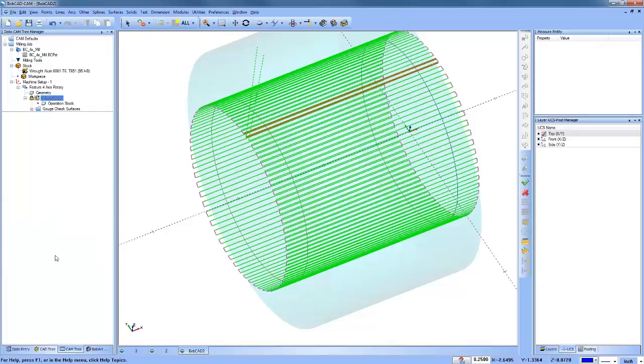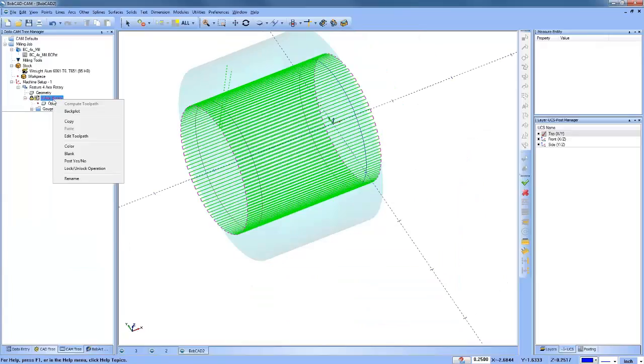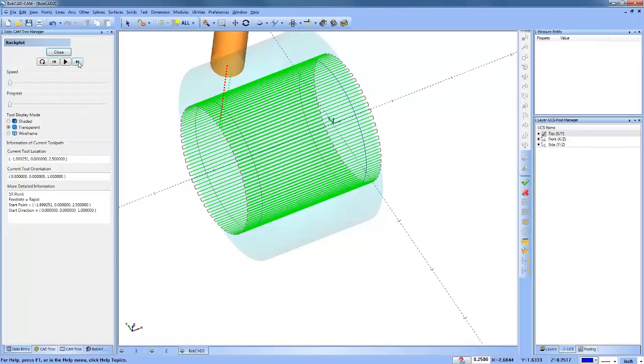Apply all. Okay, so what we've done is on this cut here, this first move, we've slowed down the feed rate. Then after it gets through this section here, it's going to speed up again. So as it's engaging through that first cut, it's slower, and then once it gets into the cut, it can speed up its speed rate. That's just a quick example of how you can edit things on the fly.